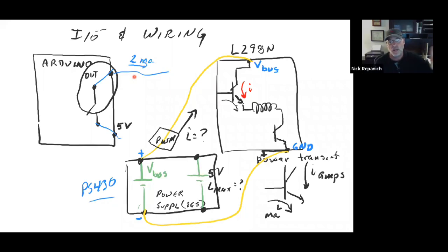At least twice a semester when I was teaching 140, somebody would have this happen. Somebody blew up like a $3,000 controller last year because a wire came off because they had just kind of twisted it together and they were sloppy. The wire came off and it flopped around until it found the circuit board. And then it shorted out the whole thing.